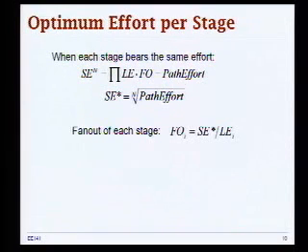And the stage effort is the product of that fan out that we are familiar with, and this new metric that we introduced, logical effort. Simply then we can say that stage effort is the nth root of this path effort that is calculated as a product of logical effort of all stages and the total output to input capacitance.